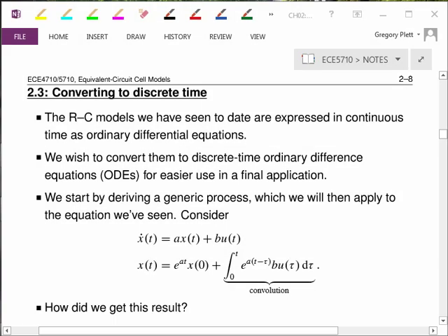The equivalent circuit model that we have developed to date has a voltage term that describes the open circuit voltage as a function of state of charge. We have an expression then that gives us state of charge. We also have a term that describes the instantaneous voltage drop when current is applied. And we have a dynamic term, this resistor capacitor or RC term, that describes the non-instantaneous dynamic effect of applying or removing current.